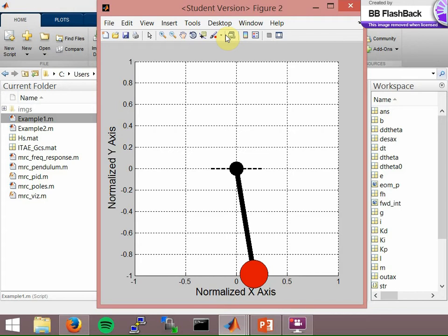Yes? Is that like over damping, under damping, that kind of thing? No. So when you talk about damping, that's inherently a stable system. So that means that if you do damp something, you have a nice steady oscillation behind it. That's under damped, right? So it's not over damping and it's not under damping. This is actually something entirely different. This is stability, right? So this is important. There's a chance that our controllers can drive our systems to instability. That's not good, right? So the most important concept in controls is stability.